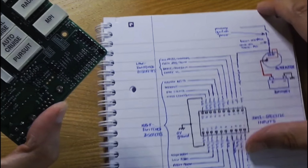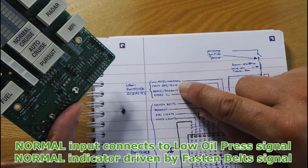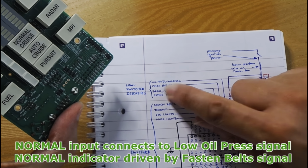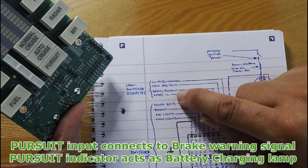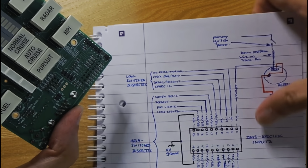as indicated in this diagram here. The normal indicator will actually represent oil pressure, low oil pressure, if we have a fully functional mode. The auto indicator will correspond to the check engine light, and the pursuit indicator will correspond to the brake warning light.